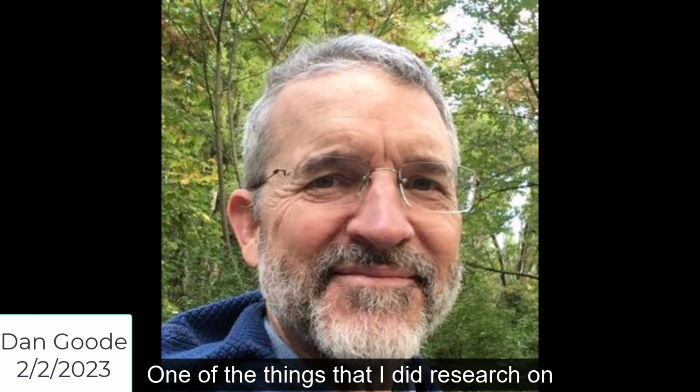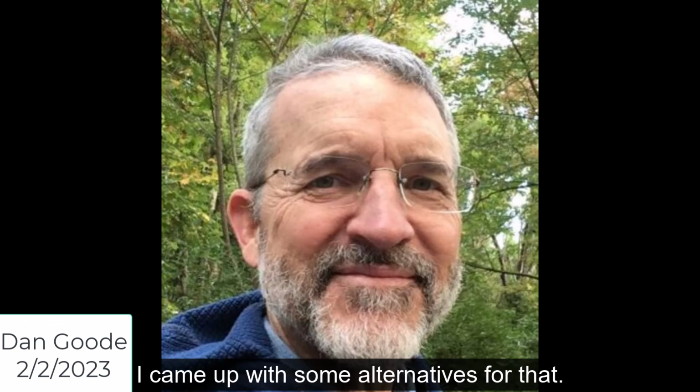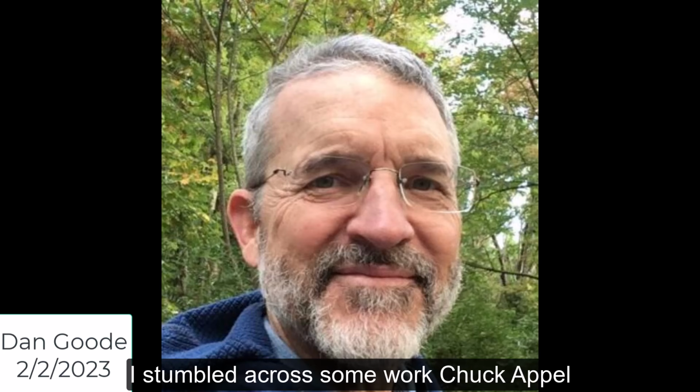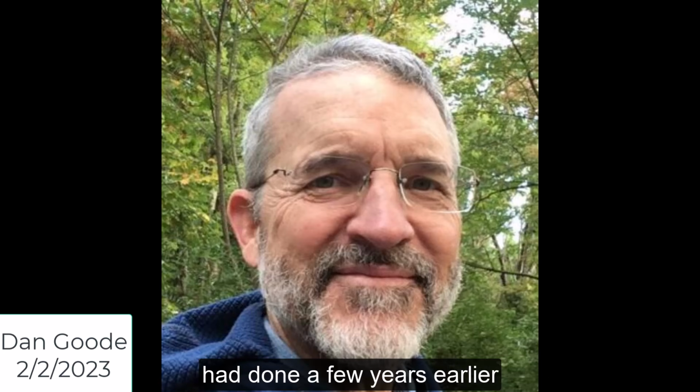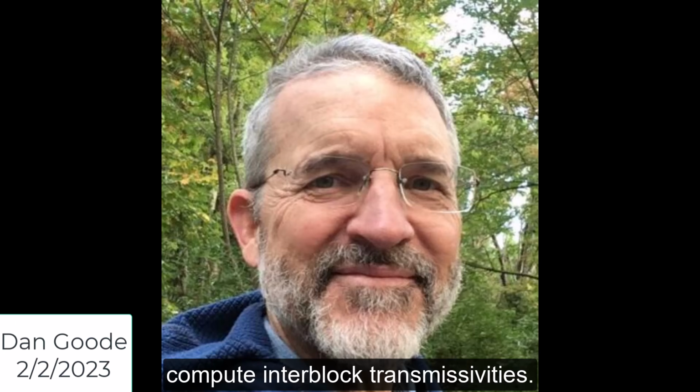And one of the things that I did research on was the particle tracking method used in the MOC model. And I came up with some alternatives for that. But in the process of doing that, I became interested in the way that hydraulic connectivity variability was accounted for in the finite difference flow model, and stumbled across some work that Chuck Appel had done a few years earlier about the same topic, not the particle tracking, but how do you compute the interblock transmissivities. I did a little bit of research on that.